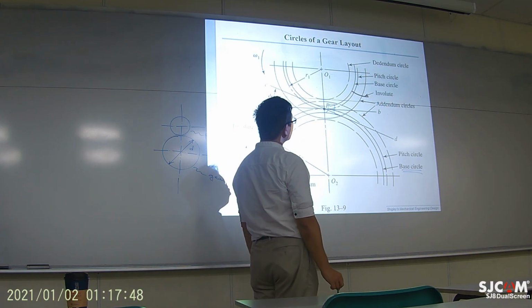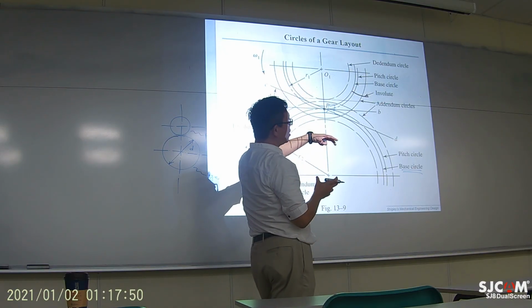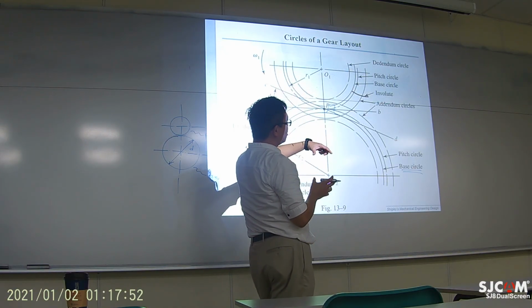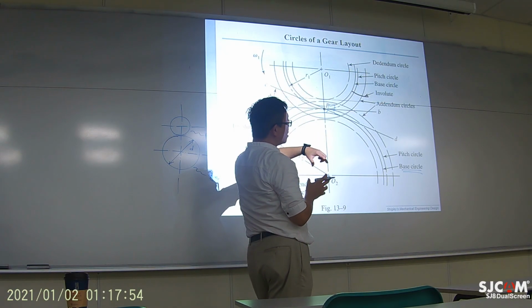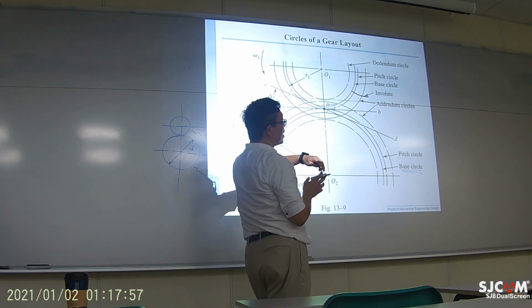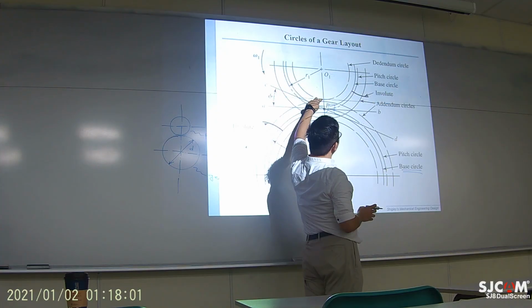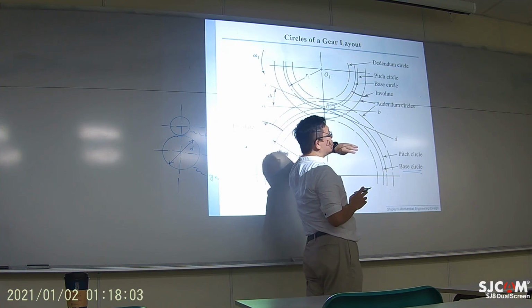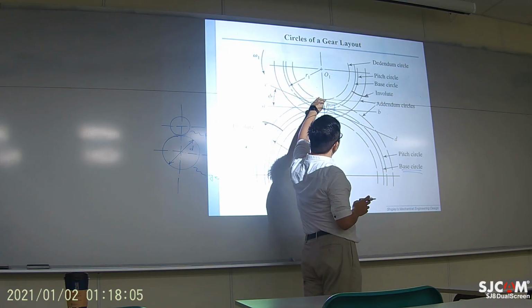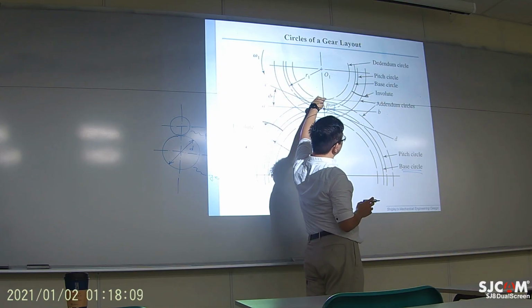And you are not supposed to have a tooth that is too long. Otherwise, you may have collision with the base circle on the other side.